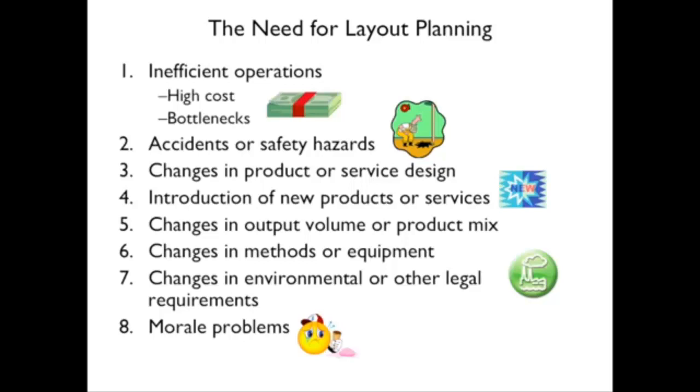When you change the output or product mix, where you're going from low volume to high volume, or maybe high volume to low volume, the layout could change. When you change methods, you change equipment. And then the environmental or legal requirements: everything's working great, and then there's a new law where you have to do something different. Maybe it's OSHA, it may be pollution or something like that. And then morale problems. You want to keep the employees happy, and sometimes just changing the layout will make their job easier, make them happy.